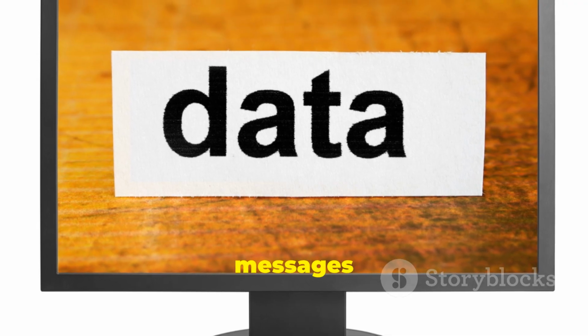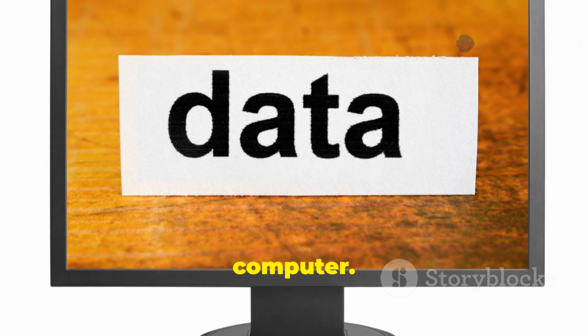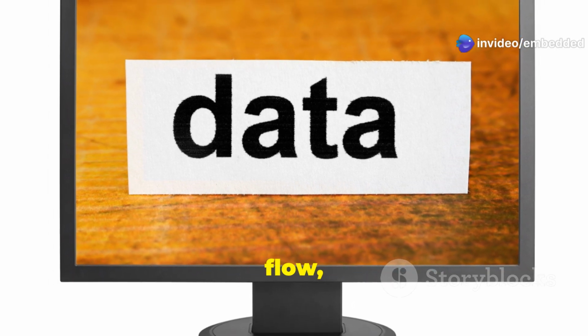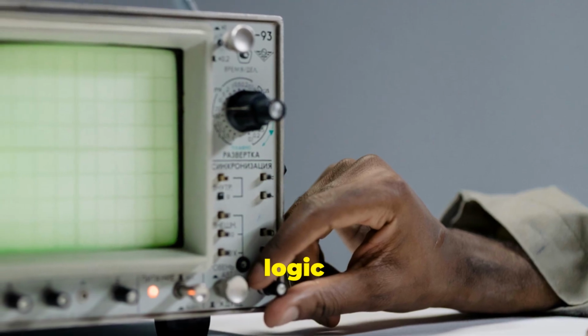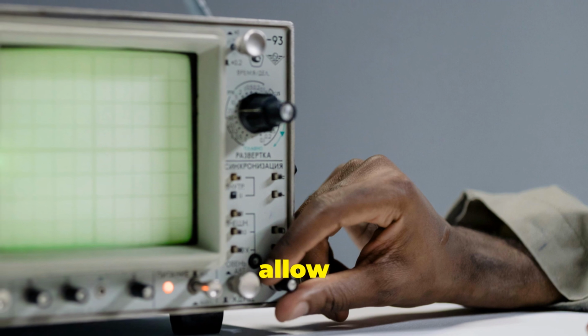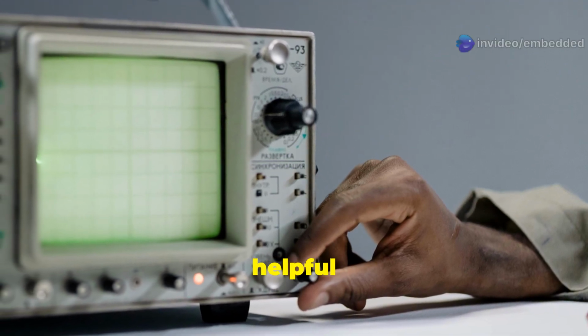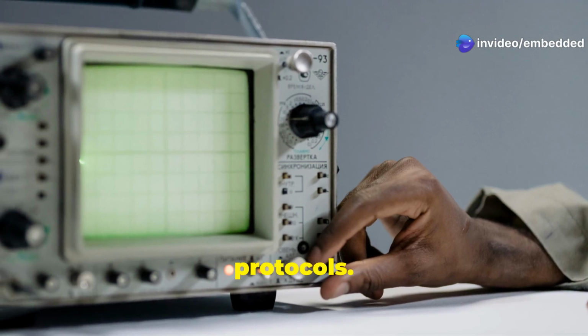Printing debug messages: you can use a serial port to print messages from your embedded system to a computer. This is helpful for monitoring variable values, program flow, and the status of different components. Using an oscilloscope or logic analyzer: these tools allow you to visualize the electrical signals in your circuit. This can be helpful for debugging timing issues, interrupt problems, and communication protocols.